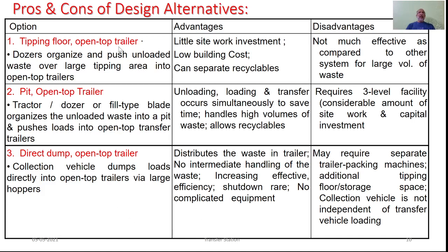So there could be a certain tipping floor equipped with open top trailers, wherein there is little site work investment, the building cost is less, and it can separate the recyclables. However, this kind of facility, which involves dozers organizing and pushing the unloaded waste over large tipping areas into open top trailers, is not very effective as compared to other systems for handling large volumes.